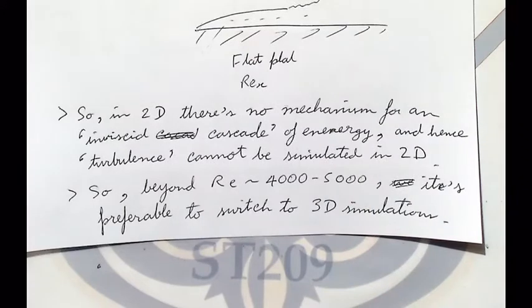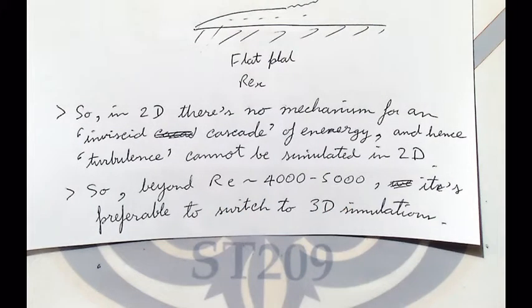Okay, and if you remember one thing, remember this. When you do 2D simulations, the Reynolds number is always limited. Anybody who shows you, oh look, this is a beautiful simulation of an airfoil at Reynolds number 20,000 or 2 million, immediately you should ask them, but this is 2D, well, what about turbulence? So keep that in mind. And for low Reynolds numbers, the simulations agree quite well with the experiments, for the reason that the turbulent cascade almost doesn't exist.